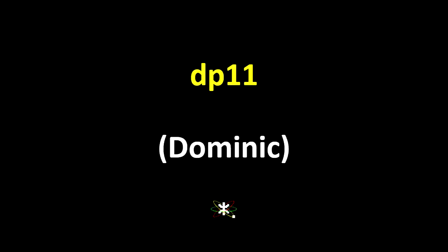So yeah, 1-bit DACs and 1-bit ADCs are quite possible. You can make a timed ADC if you ever need to do an ADC on the FPGA, because the input cells are actually pretty fast comparators at the end of the day.